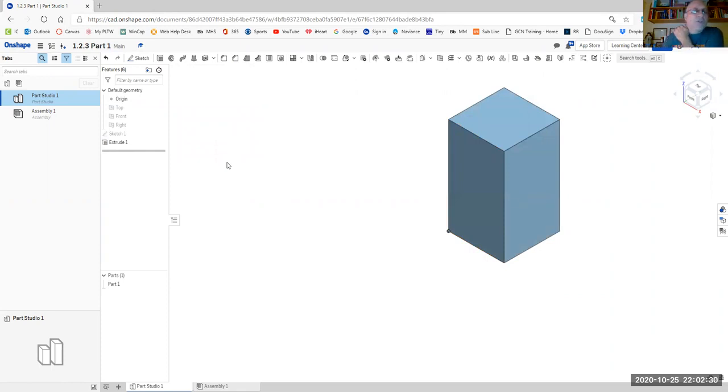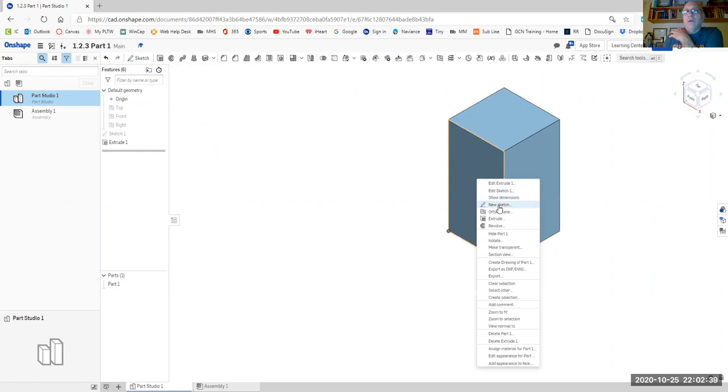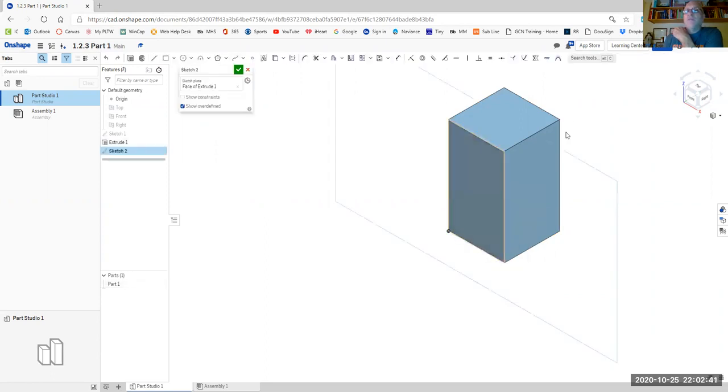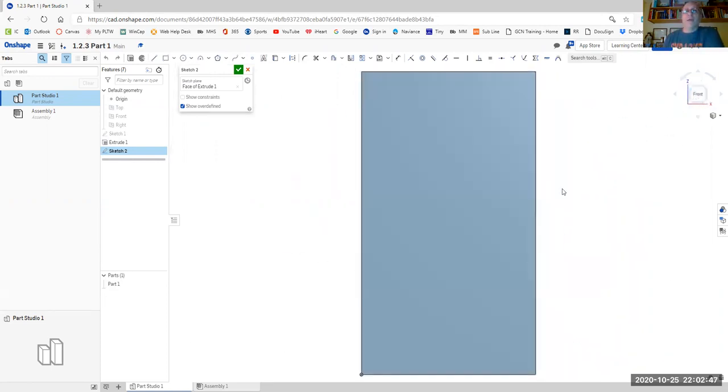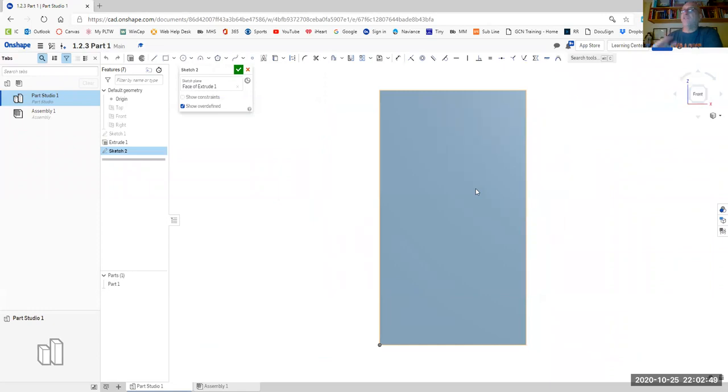Okay, we're going to do this using subtractive methods. So next I'm going to go on my front view right here. I'm going to do a new sketch so I can actually just right click and come down here to new sketch. Puts a new sketch right on the front, and then you can see my sketch plane pop up. I'm going to go to my view cube and I'm going to select my front face and flip it right at me. Now this one has a slanted surface in there. So I'm just going to go up to a line command. I'm going to start right at the top line here, and I'm just going to drag a line down to here. I'm going to hit escape to get out of my line command.